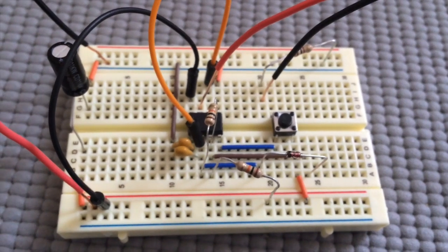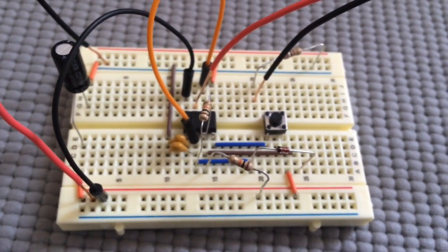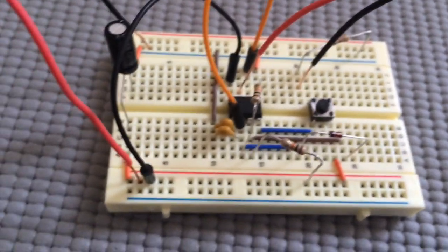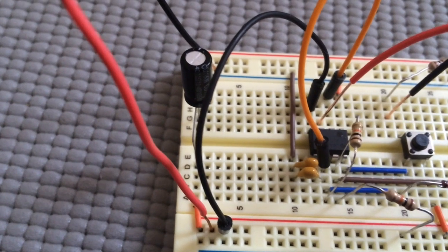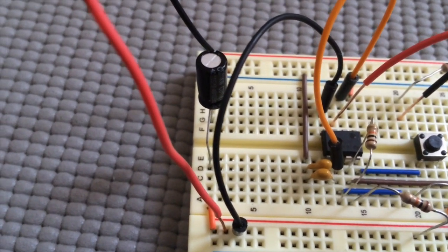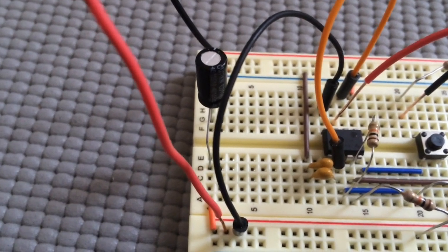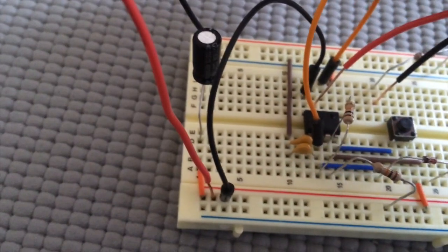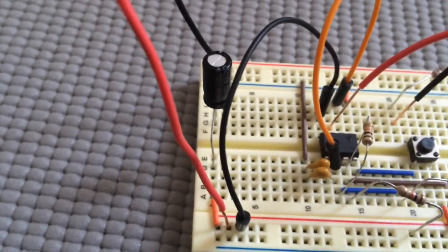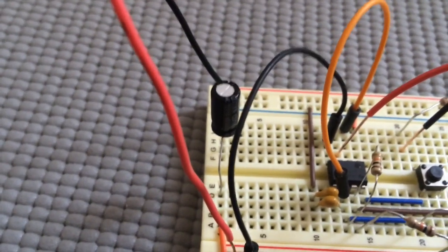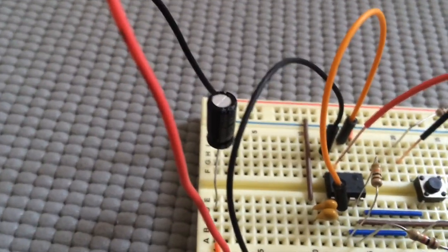This circuit is looking at the 555 timer in astable mode. In astable mode, the capacitor controlling the threshold voltage that turns off the output power is also configured to control the trigger voltage. So this causes the output voltage to oscillate.